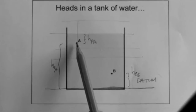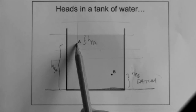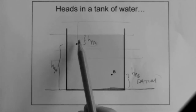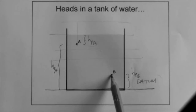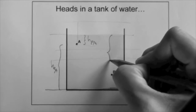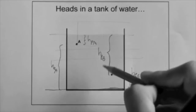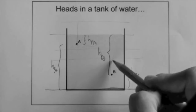Think of it as if you are scuba diving at this point. If you're scuba diving at this point, the pressure you feel is associated to this head. Okay? To this distance. If you're scuba diving down here, the pressure is higher, right? We haven't talked about pressure yet in this course, but it is associated to the pressure head, okay? Which in this case is this. Pressure head at B. It's that distance.